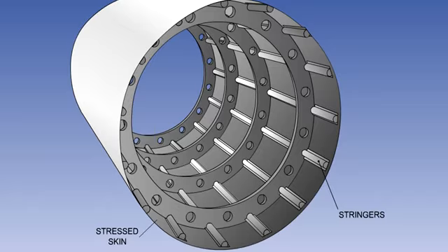As aircraft became larger and the air loads greater, the pure monocoque structure was found not to be strong enough. Additional structural members, known as stringers or stiffeners, and longerons are added to run lengthwise along the fuselage, joining the frames together. The light alloy skin is then attached to the frames and stringers by riveting or adhesive bonding. Stringers stiffen the skin and assist the sheet materials to carry loads along their length. On pressurized aircraft, they take some of the strain caused by the pressurization and convert it into tensile stress.